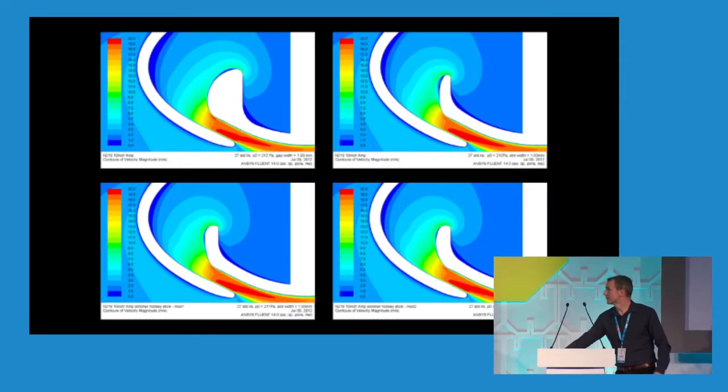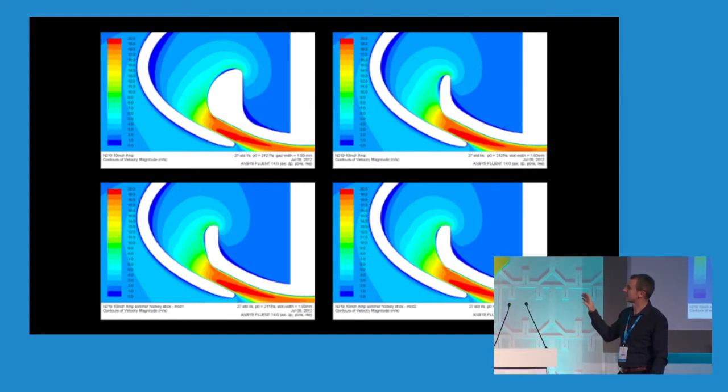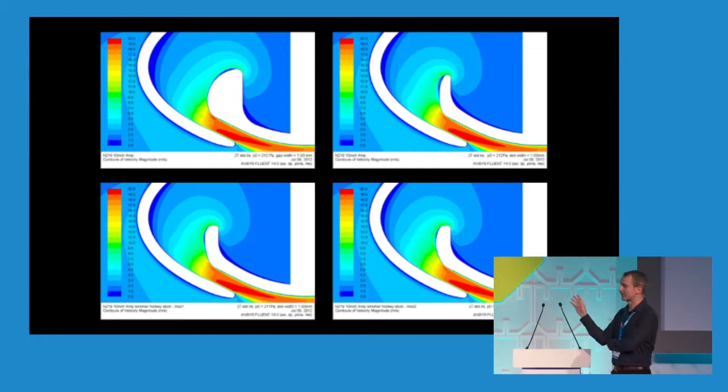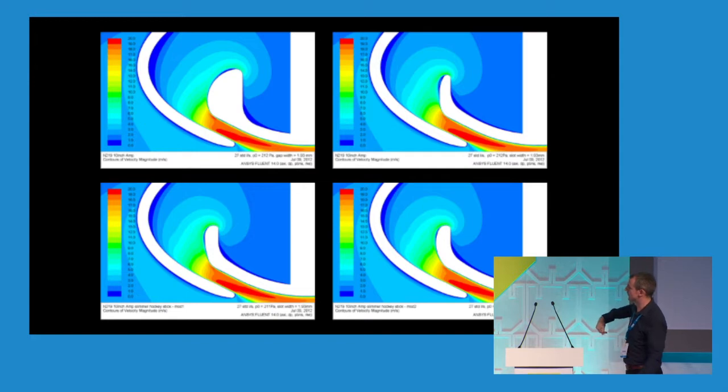The next image, which you may be fairly familiar with, is from CFD analysis. So this is computational fluid dynamics, which is a really specialist field of engineering in its own right. It uses some very powerful software programs that allow us to look in detail at some really specific areas of the product. And this is analyzing what happens to the flow inside the air multiplier as it runs around that corner, and we've got to try and get the air around that edge and through to the exit slot.